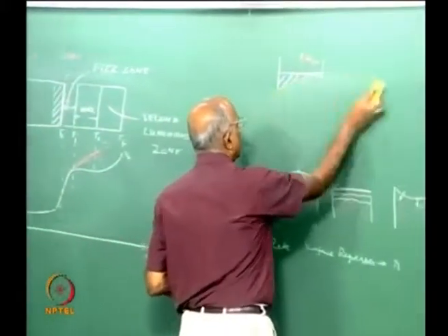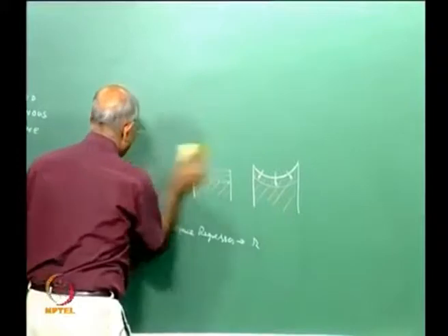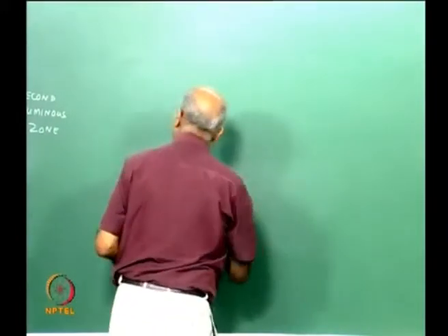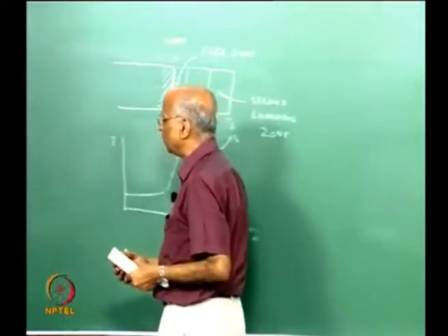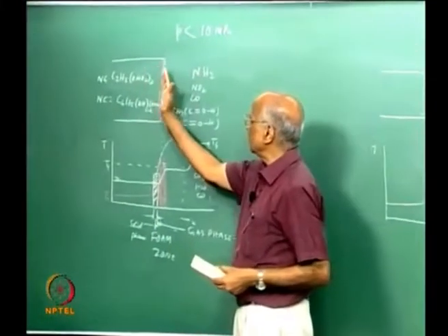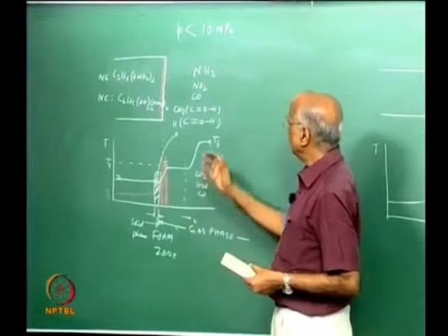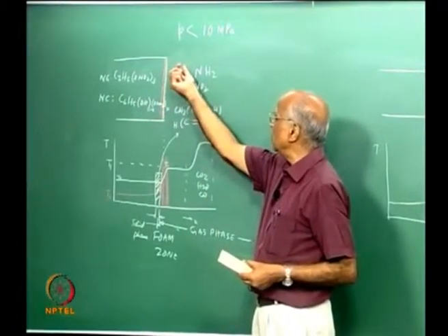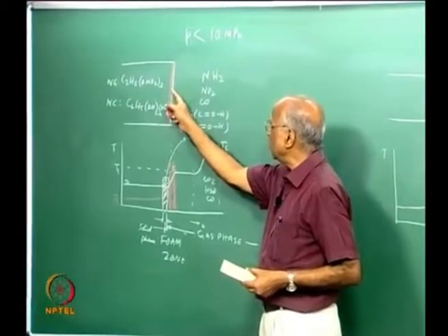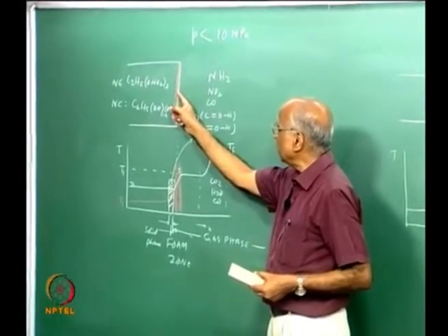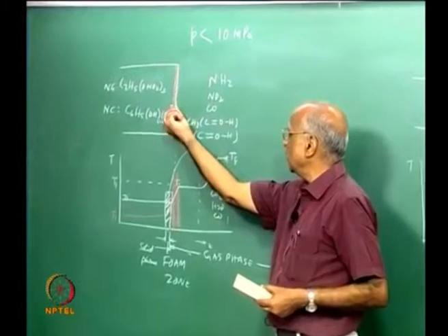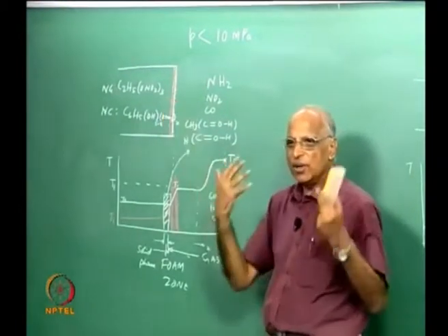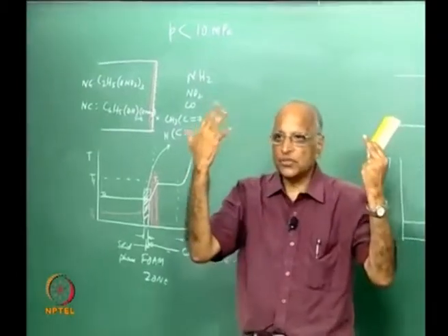In other words, what is the model, or what is the mental picture I will have in mind? For us to do any problem, it is necessary to first consider the physical problem. Like we say, we look at the sparkler and we say yes, regression takes place. We tell ourselves, heat is generated here, the temperature in the fizz zone is T1, heat gets conducted from T1 to the surface, and if I can calculate this heat which is conducted, then I can write the equation at the surface and get the burn rate. This is my mental picture of the problem.